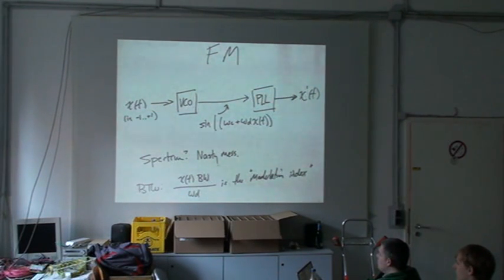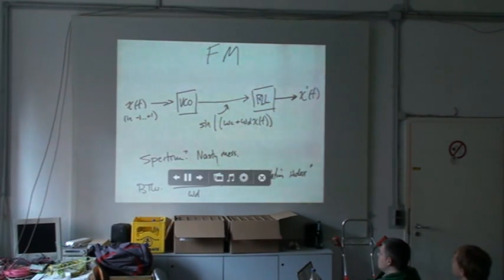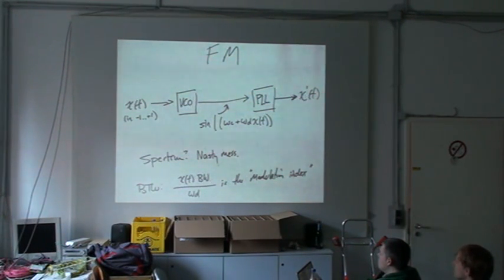Next up, frequency modulation. Here is a typical implementation of frequency modulation in a modern system. You have some information signal X that's driving a VCO. That VCO is producing some carrier that's varying with the voltage of the input in real time. That's being decoded by a PLL, and you're recovering some copy of X on the other side. And what's the spectrum associated with FM? In the general case, the spectrum associated with FM is a nasty mess. It's a bunch of Bessel functions and crazy stuff.